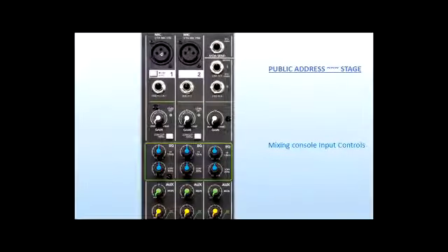I forgot which ones they are. On here, okay? So if you take a voltmeter, you're going to find 48 volts DC on that if the phantom power is on. So what happens if you plug a dynamic microphone into it? Is that going to damage it? No, it's not going to damage it. The dynamic microphones are designed to ignore the phantom power. Okay?